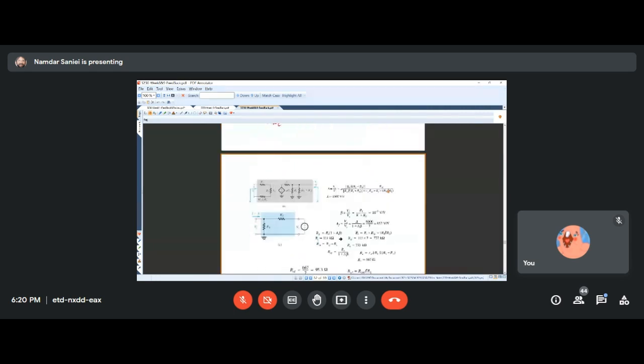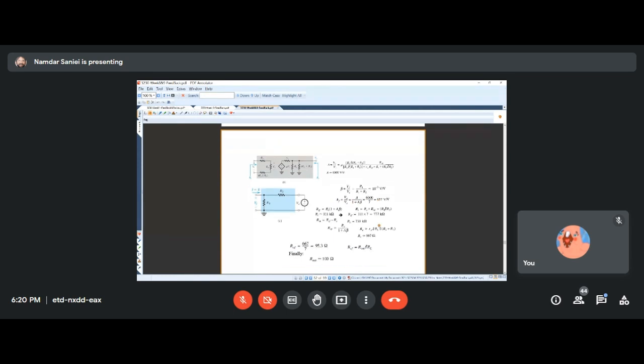We also brought R11 and R22 into the amplifier, forming the newly formed amplifier. We had to find the gain of it, and also from the feedback network we had to find beta, put them together in this formula, and we had the gain with feedback.